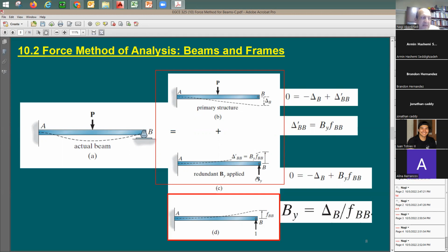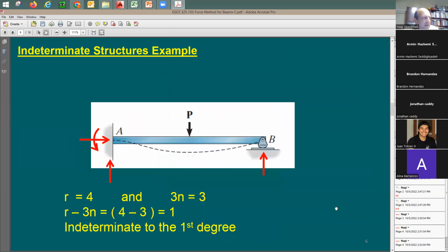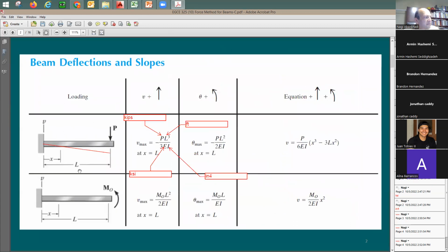So what happens if I take this beam, this case, and of course remove this point load. I'm going to take this beam and just put one kip. You remember the one system and the zero system? If I put one kip here, I'm going to go to the standard beam, the pre-solved ones. Let me go back. Yeah, this one. But instead of the point load coming down, I'm going to make it go upward. Can you find out the deflection? You can say, yeah, I have an equation for this.